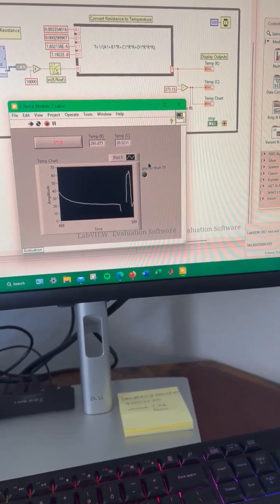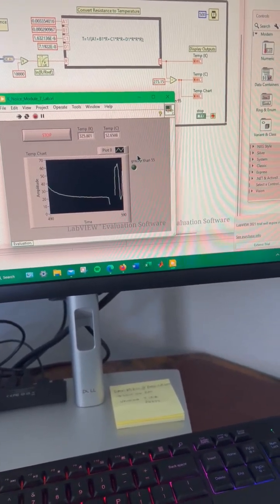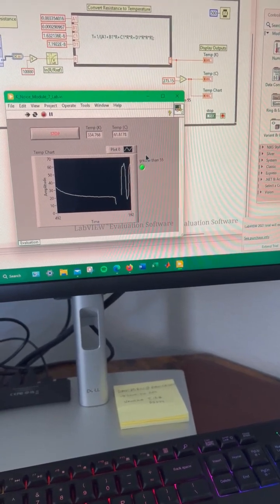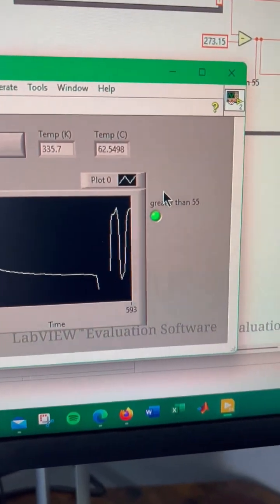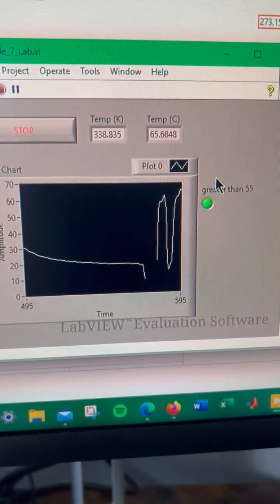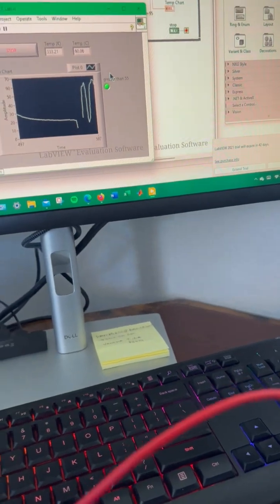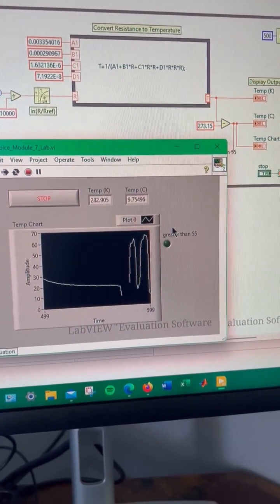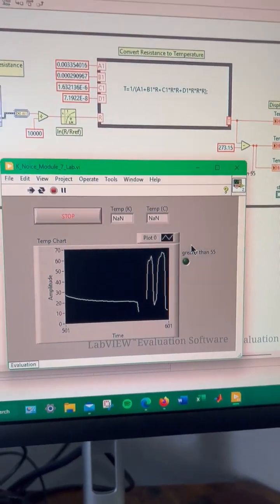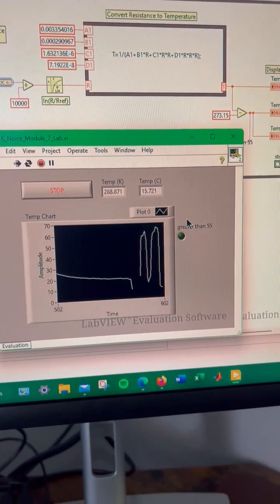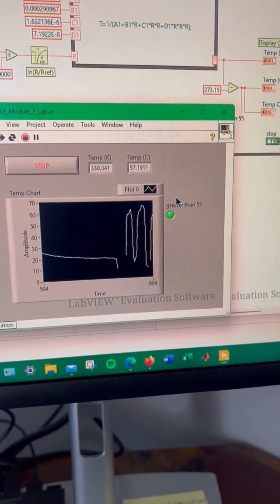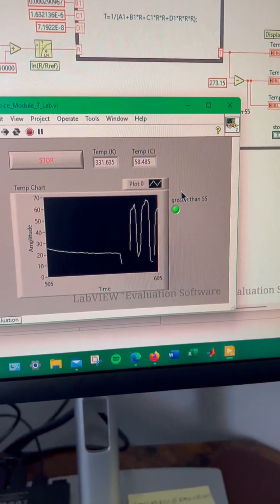And we'll go back up to the hot water, and then we see our resistance bing, and then greater than 55. And then that's obviously linked to the Celsius. And then we can minus 273.15 degrees from that Kelvin there, if we want to get our delta. Go back up, and then we can see our temp chart there changing, and we see our thermistor picks up the temp change pretty quickly.